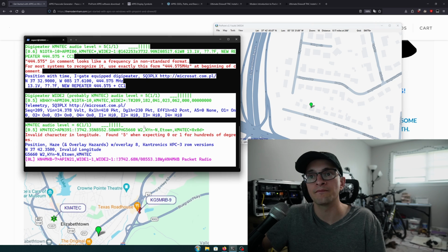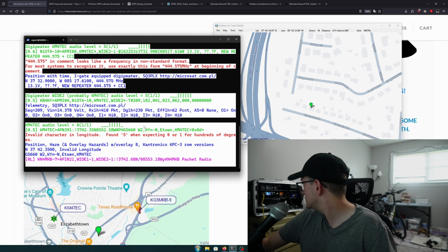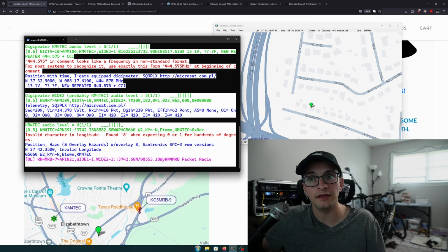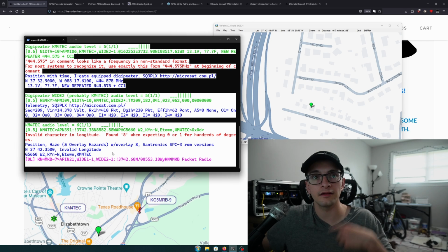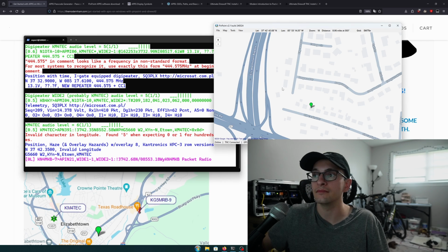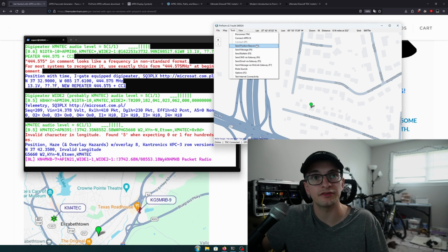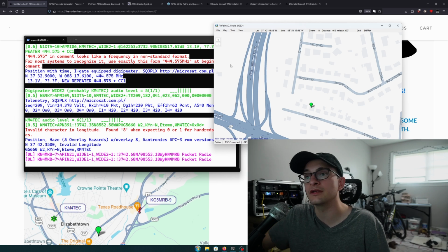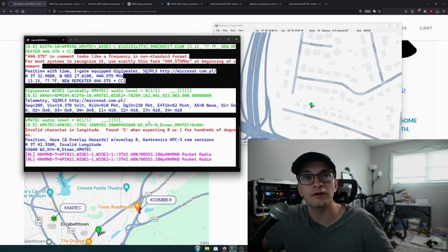If everything goes right, which it looks like it did, I saw my radio transmit and key up. Direwolf showed purple; remember we talked about that meaning transmitting. We sent a position beacon. As annoying as it might be, I'll send another so you can see it. I'm sending with low power too, so ordinarily you'd probably see something back from a digipeater if there was one around.